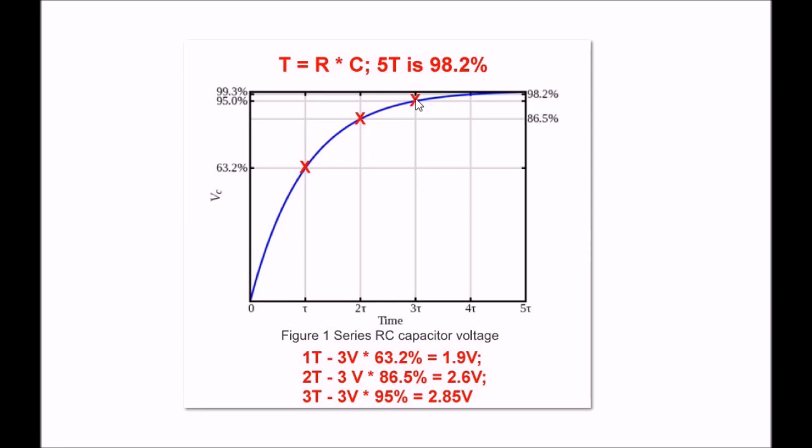What is the additional problem? Maybe you have some really good MOSFETs and they cut on somewhere around 2T right here. But what if you had 4 MOSFETs in parallel like I showed earlier? MOSFET 1 fires here, MOSFET 2 fires there, MOSFET 3 fires here, and finally they're all firing when we reach here.